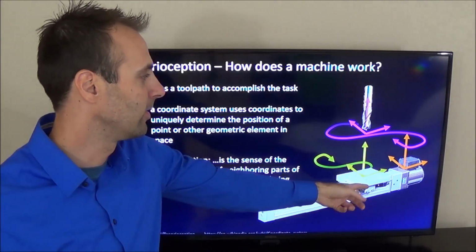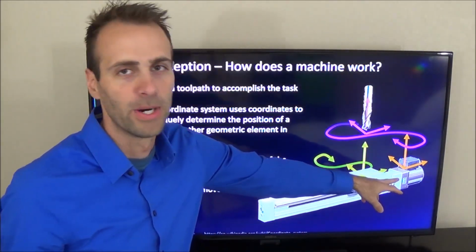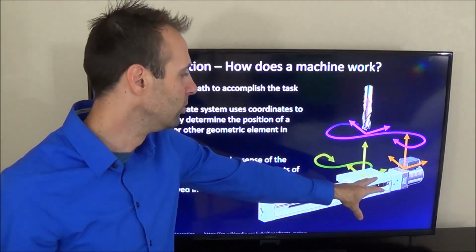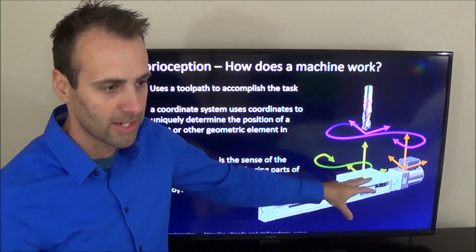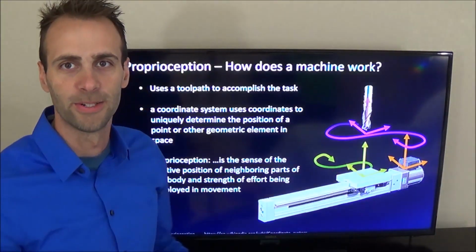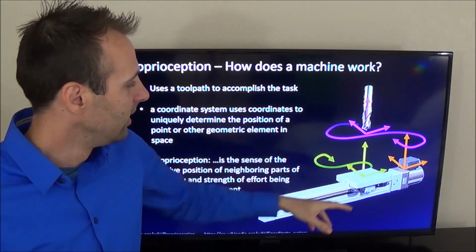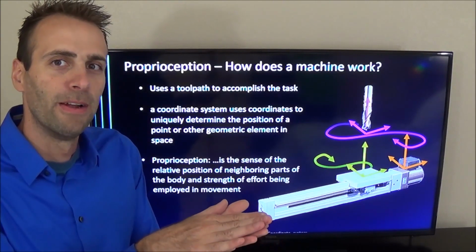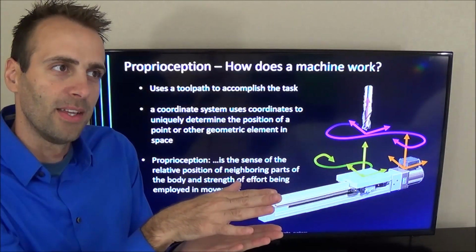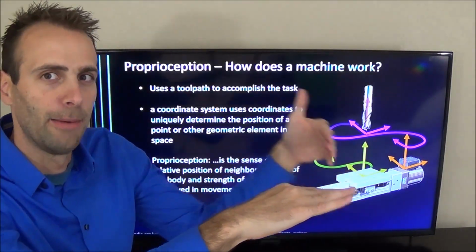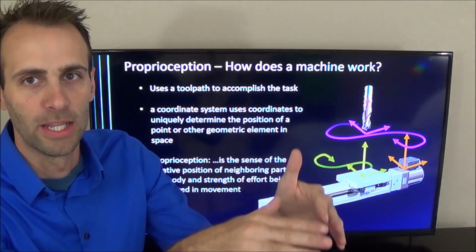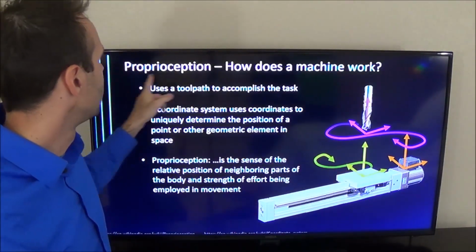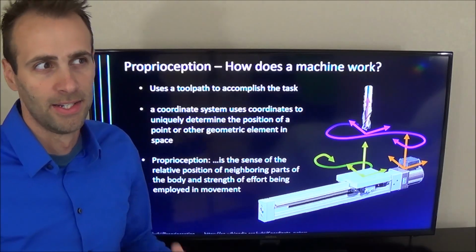Obviously you know if this is a stepper motor how many steps you need to move my axis 1 inch or 1 millimeter, whatever. But then the error component says, well, I also know that if I move 1 inch, it's going to twist a little bit, so I need to compensate with another axis to bring that back. And that's this concept of proprioception, right?